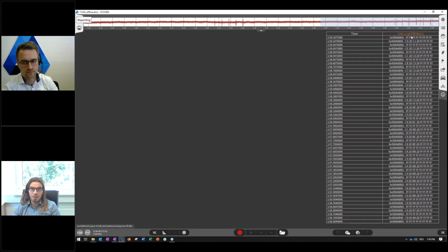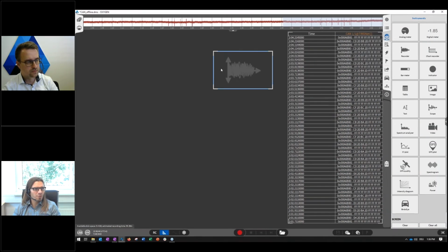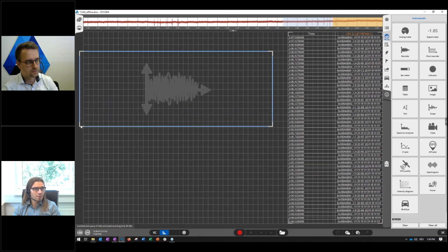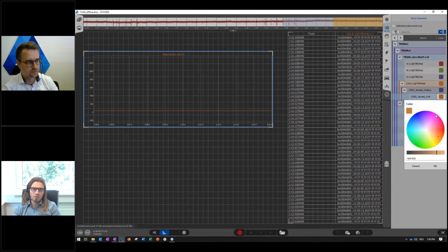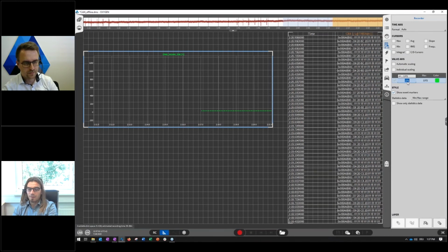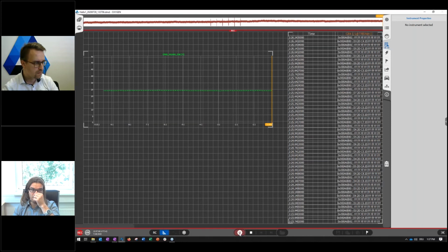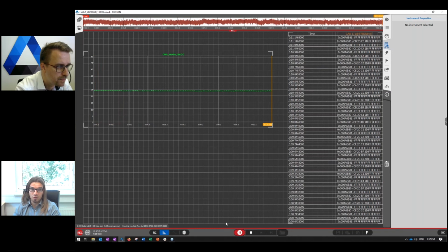During the measurement, I can now visualize this data with a recorder, for example, place it here on the screen. And I'm now applying the signal here from channel 0. Just change the color a little bit and also change the scaling. And now only this channel is decoded during the measurement. So I'm now starting the measurement for a couple of seconds. The raw CAN data stream will be decoded and stored, but only this channel here will be decoded and no other channel.